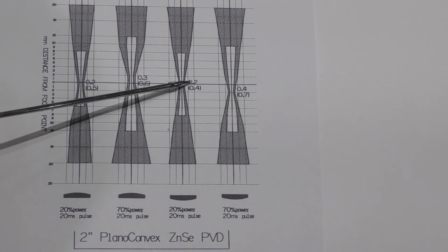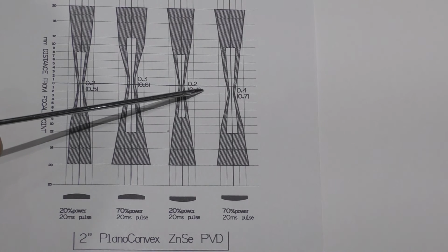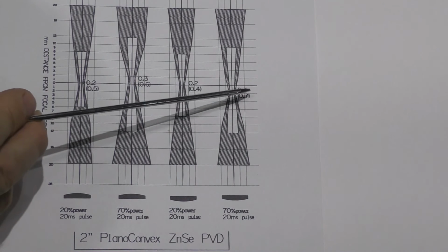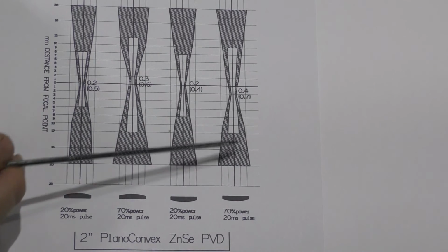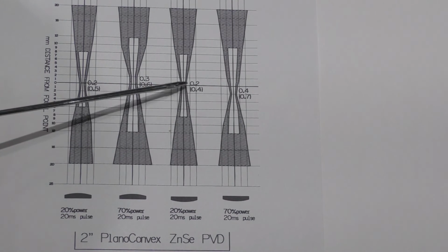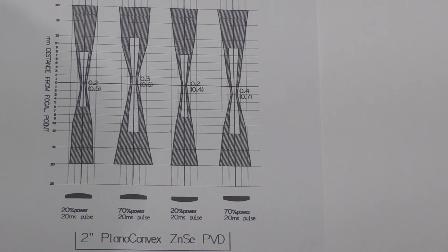We started off with a 0.2 and a 0.4, 0.4 being the scorch mark, to which we add another 0.12 just to allow for the beam. But now it's gone from 0.5 up to 0.8 when we double the power, and the hole has doubled in size as well, from 0.2 to 0.4. So the spot size appears to be a variable device.